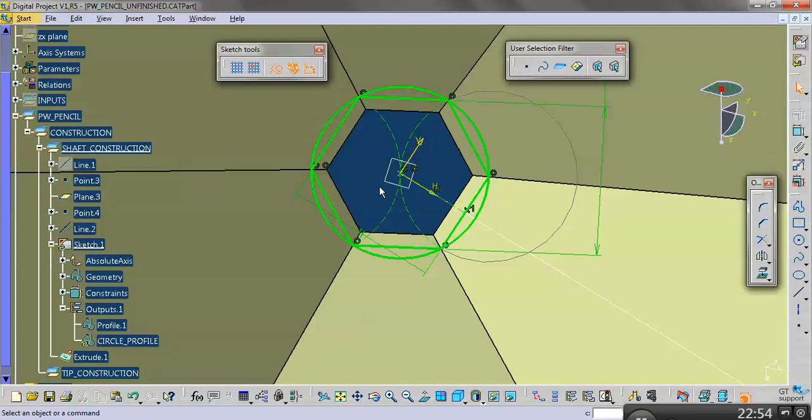If you want to make 6 intersections because you've got 4 lines, or 4 intersections because you have 4 lines, if you double click intersect, you can just hit line, line. It'll make an intersect and give you the dialog box again. Line, line, make the intersect, give you a dialog box. If you want to make a bunch of points, just double click point and it'll give you the option to make all kinds of points.